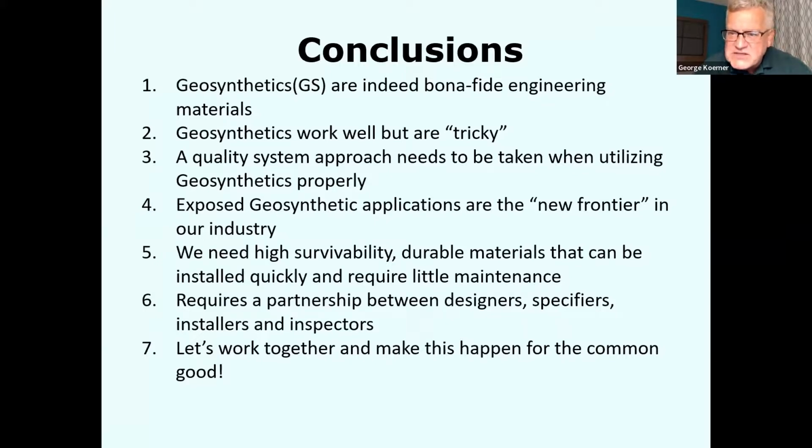Obviously, you could place soil over top of it and get it away, but those are your three areas of attack. One, making a nice formulation. Two, coating it with a spray applied material. Three, putting a permanent cover. And certainly the GCCMs or turf or HPTRM could be placed over top of it to cover it or shade it.